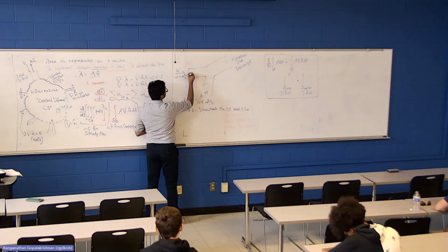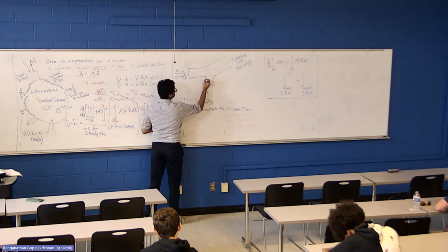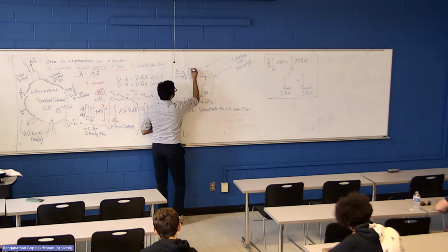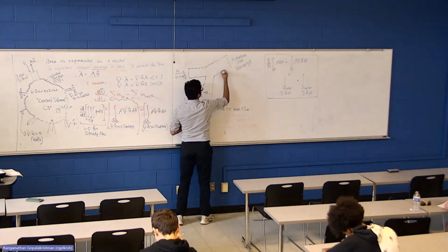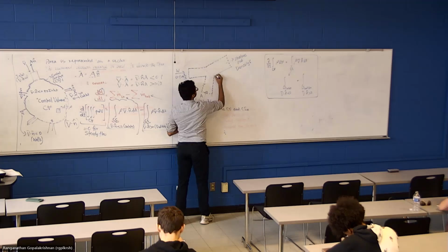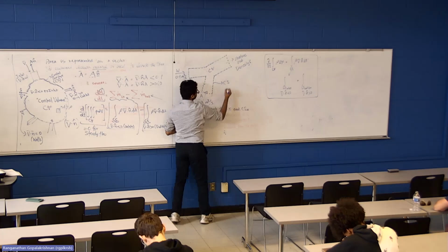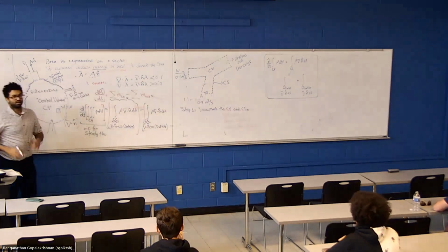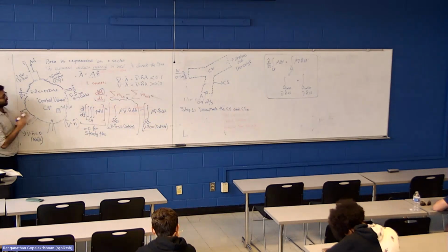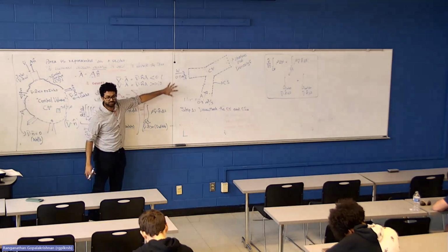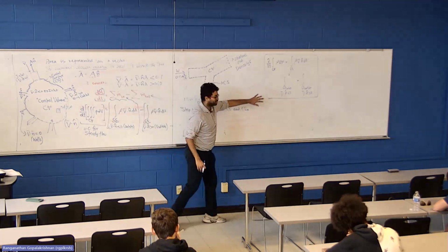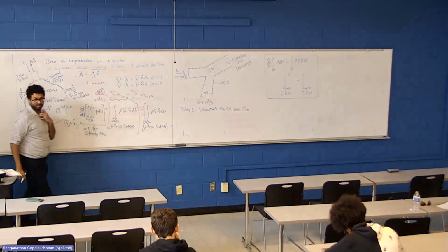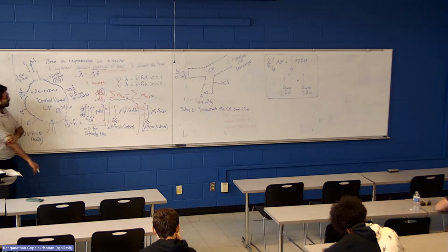So I will choose the volume that coincides with the Y duct as my control volume, and the dotted line shows the control surface. It's really important you have a clear idea which is your control volume so that you can apply those equations correctly. So start with marking the control volume and control surfaces.